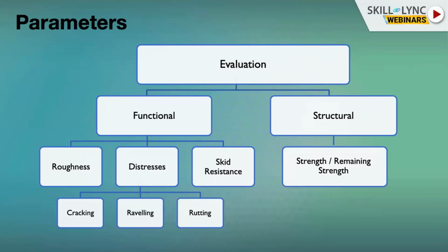So the structural evaluation is done, and of course we will measure the thickness, but the thickness is not a time dependent parameter. The time dependent parameter in terms of structural point of view is the strength. As the life of the pavement goes on, the strength of the pavement will go on decreasing, right? Because of the continuous application of the load. So we need to evaluate what is the remaining strength to assess the load bearing capacity of the road.